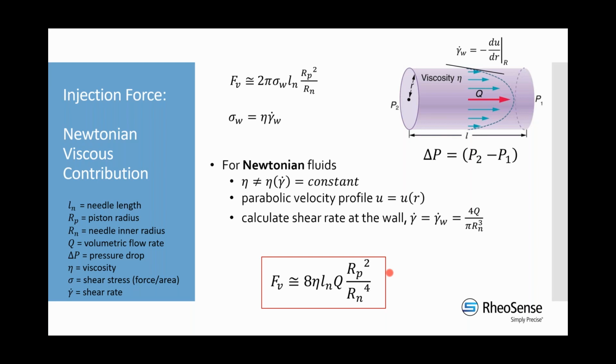So I wanted to, at the moment, just step away from the PowerPoint and go to our analysis software, which does all of this injection force prediction automatically for Newtonian fluids. Just so you can get a feel for what our software is doing, but also to see how easy it is to use that software to make some adjustments to your parameters. So if perhaps your fluid is fixed and you can't change viscosity, but you have some flexibility in your delivery parameters, you can use this software to see how, say, changing needle gauge or changing what particular volumetric flow rate you want to deliver the product at impacts this injection force.